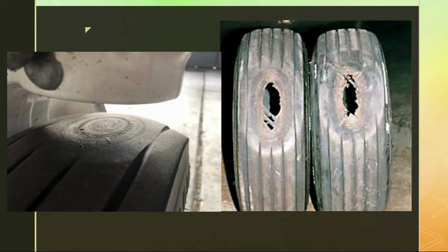So you need to be very cognizant, pay close attention to not tensing up your legs and not getting on the brakes too much. I will say one of the things you need to do is not have your feet on the brakes at all when you come into land. Have your heels on the carpet, have the balls of your feet on the rudder pedals, and that will, even if you do tense up a little bit, you won't accidentally use the brakes because you're not touching the brake pedals.